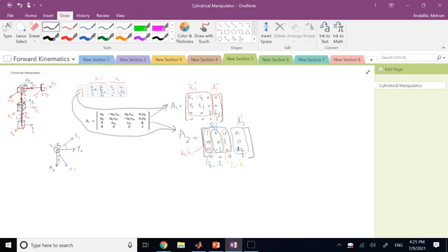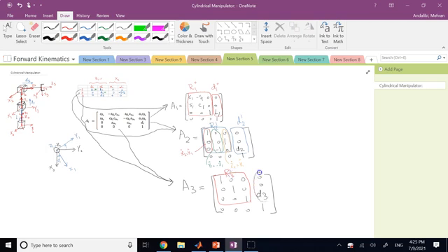And finally, you go and look at the third row with this formula for the A matrix, and A3 is going to be 1, 0, 0. Your rotation matrix is exactly identity in this case, and your displacement is simply 0, 0, D3. Of course, because if you look at frames 2 and 3, there is absolutely no rotation, no twist, nothing. So the rotation has to be an identity matrix. And D of 3 with respect to 2 is only determined by the prismatic joint value of d3.